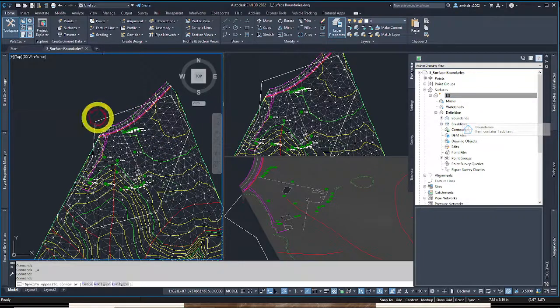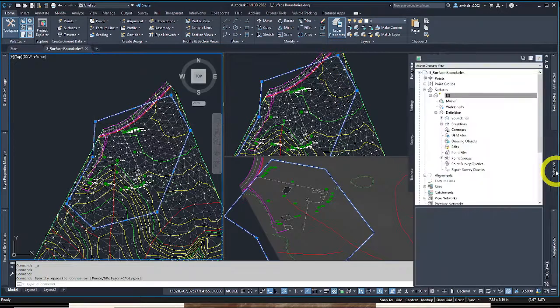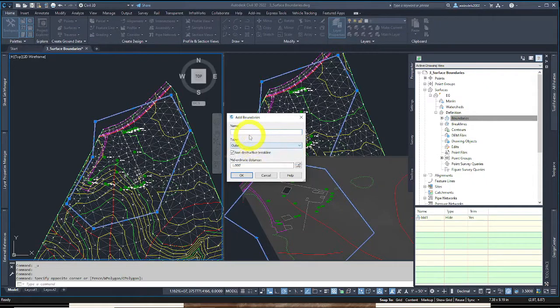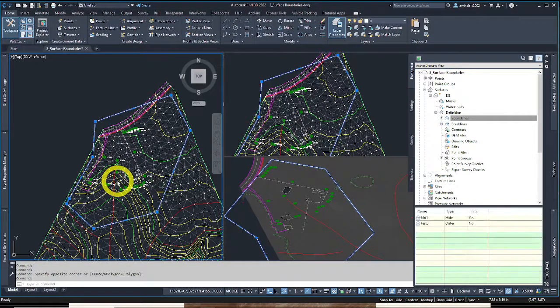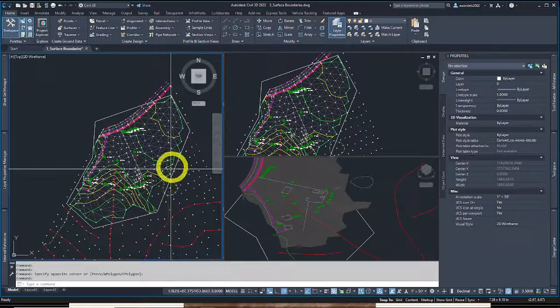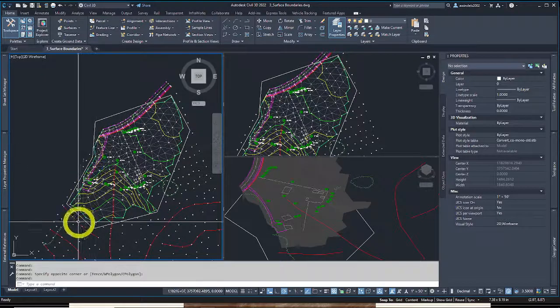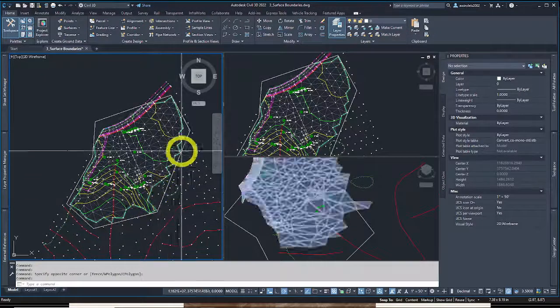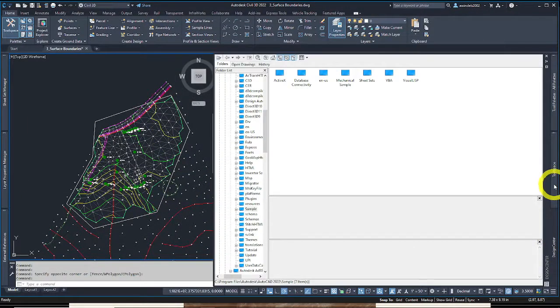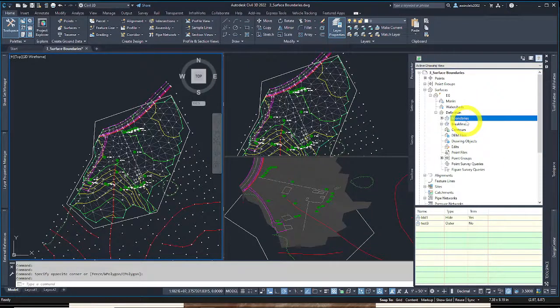Let's add the boundary again. Let's pre-select it the other direction. Instead of selecting the surface first, let's add it again. This time, let's add it, yes, as an outer. Let's call it test 3 this time. Let's turn off the non-destructive and you'll see the difference. It takes a minute to retriangulate. It just kind of made some jagged edges, basically destroyed the edging of the surface. It didn't project it out around. So in general, we want to leave that non-destructive on. So it's non-destructive.